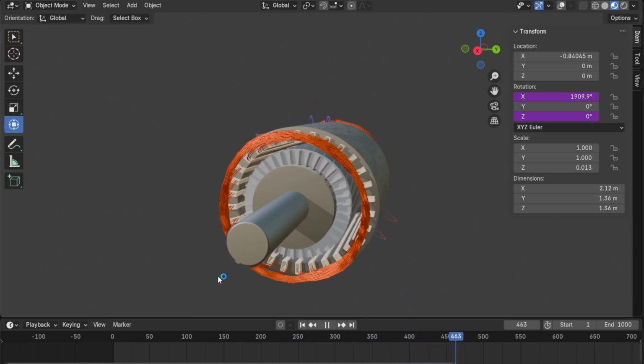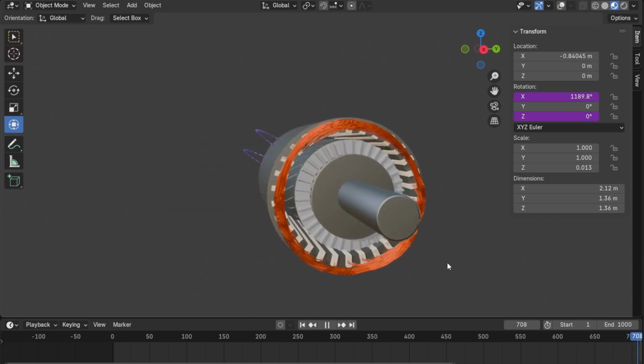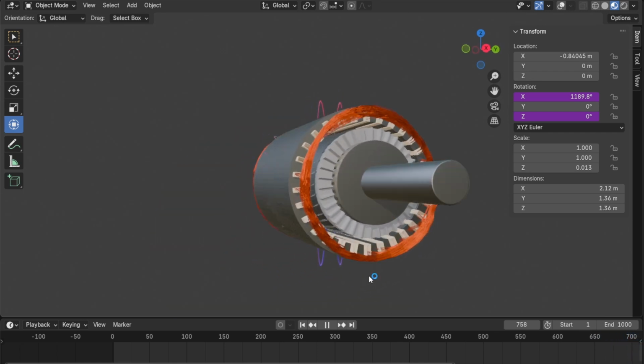And if that happens on one leg on a three-phase motor, yeah, it can still work sometimes, but it's going to be single phasing. You're going to put more stress on these other windings, and it's just not good at all. Single phasing a three-phase motor is not good. It might work, it might start up sometimes, but you're really harming the motor.